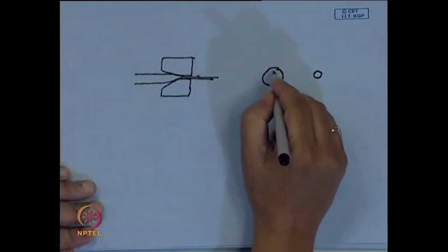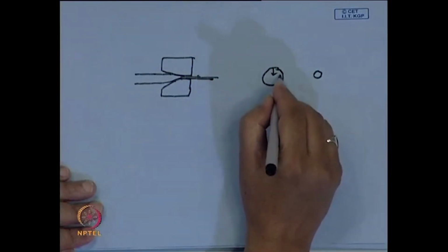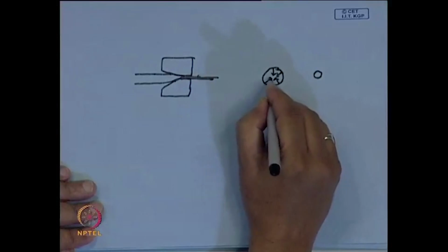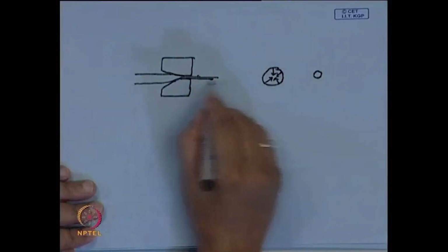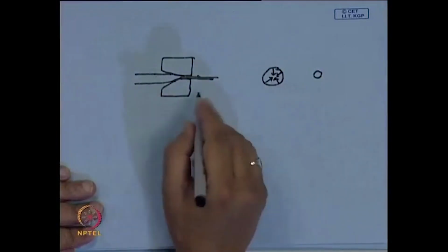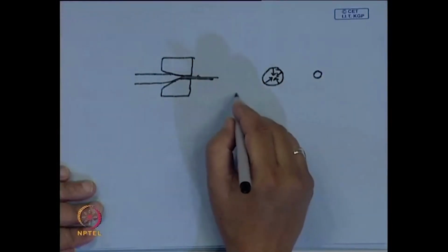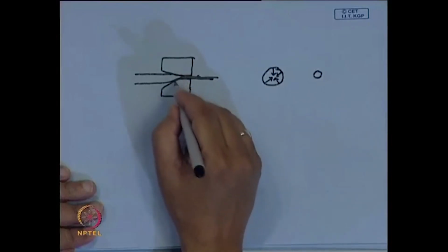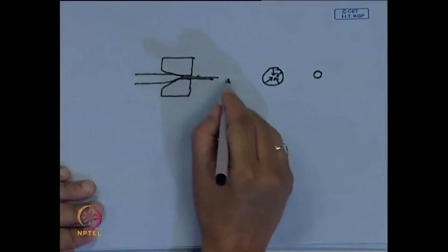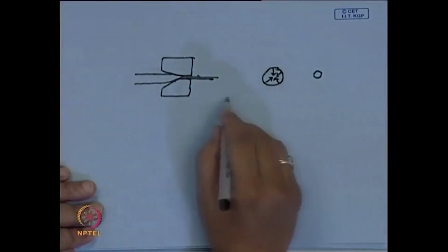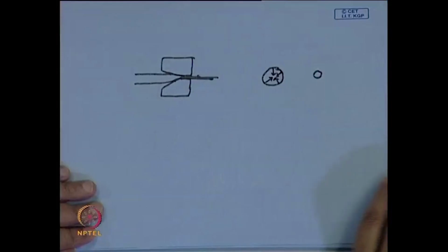So, there is deformation in these directions, where the diameter reduces and the length increases. You can say that drawing is a process where you have reductions in two directions and elongation in another direction. And we also assume that volume does not change during deformation.